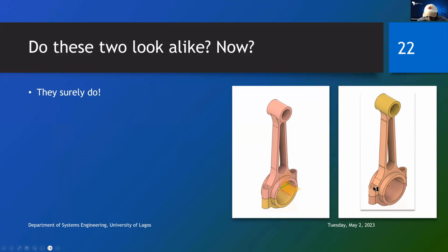whereas in this place, the hole that we put here for the pin did not cut into the larger cylinder here, but this hole cut a little bit into this cylinder. So you can notice that if you just take a cut through it. If I can quickly get to the Fusion 360 file, I can do it for you to see and compare the slicing through both of them. You'll see that this is narrower, and therefore this cylindrical object here with this small thickness, there is something that cuts part of it here, and here it is completely free of the cut of this hole.